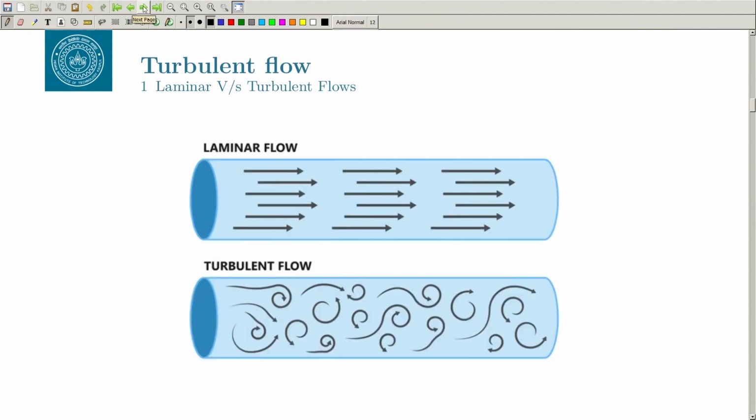So, this is what I was saying, that this is the typical picture of the laminar flow. If the flow is happening in the laminar region, if it goes like this, it will continue to move in that line, but in the turbulent flow there will be a lot of mixing, right. There will be, I use the term eddy. You can see these shapes here; these are basically your eddy shapes. So, what they do is a lot of mixing, and depending on the Reynolds number there will be violent mixing from top to bottom, and that actually develops additional stress also. Typically you would hear that turbulent flow has higher drag, right. If there is a wing and the flow is turbulent, the drag is higher. Why? Because it develops higher stress, that is because of the momentum that is being transferred by these eddies.